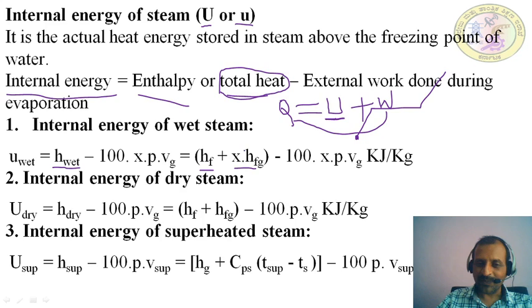The next one is enthalpy entropy diagram or Mollier diagram. It is called Mollier diagram. So what do you mean by this diagram? This is the graphical representation of, once again, steam table. So in the earlier slide we have seen there is the steam table, the properties values are tabulated in the steam table. But in the graph it is given in graphical representation. Only that is the difference. Mollier diagram is nothing but a graphical representation of the steam table.